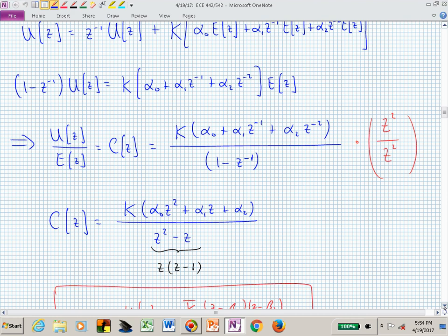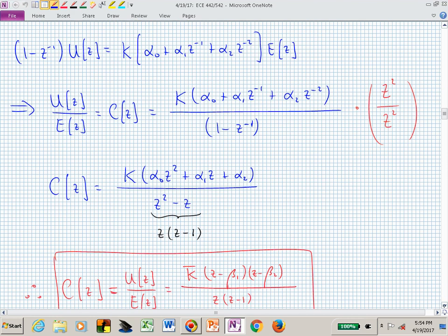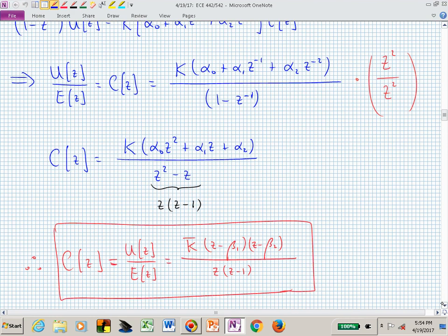And I hope that you can see that now in this PID controller structure in the discrete time setting or in the frequency domain, I don't have any freedom to move the poles or the pole factors. Where are my poles in this PID controller? I have 1 at the origin. Z equal to 0 will cause the denominator to vanish, and Z equal to 1.